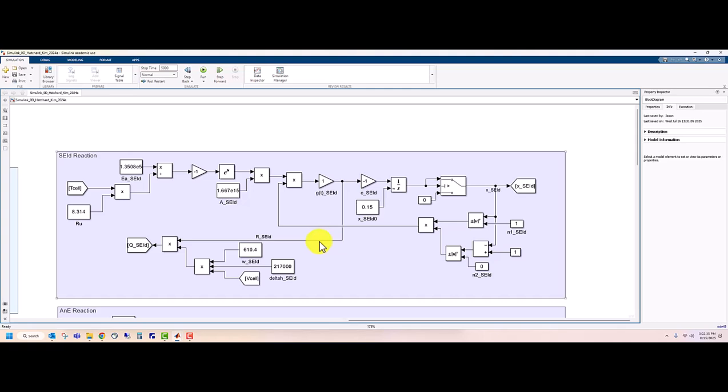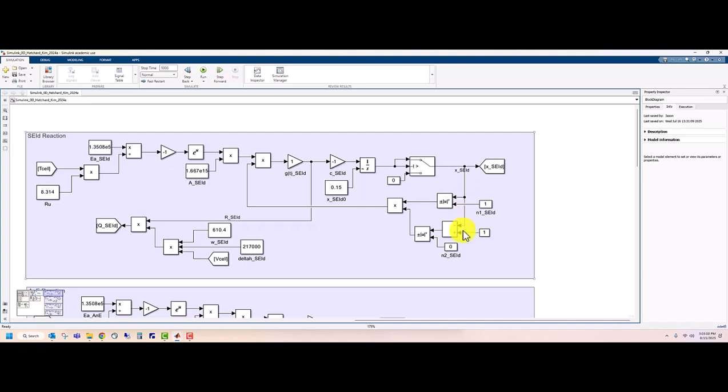It should be noted that the reaction rate is pulled off here and is used to calculate the reaction heat. We have some additional parameters needed to calculate that rate of heat generation. The R, the reaction rate, is then multiplied by C. That's our bookkeeping parameter. It's either a +1 or a -1, depending on the reaction. Over here we have some reaction orders, and really the rest of the ordinary differential equation is here.